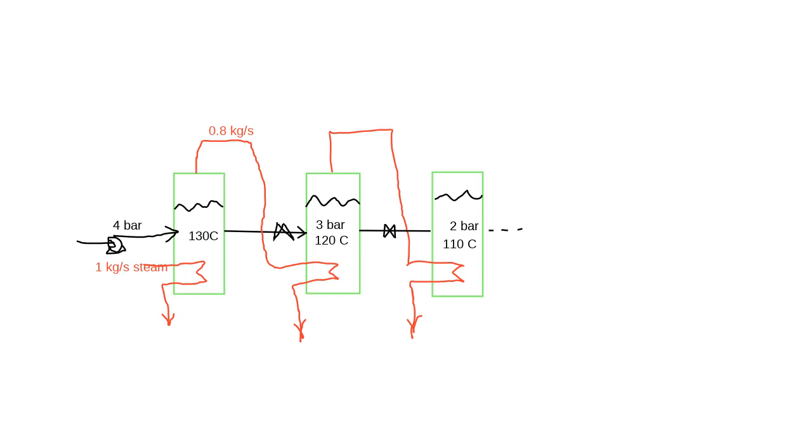This sugary stream that's coming in here is evaporating more and more water, so the flow rate is getting less, and that water is essentially coming out as condensate. The water that's part of the sugar solution comes in as liquid, and it's exiting as liquid over there and over there, and in all of the effects further down from that.